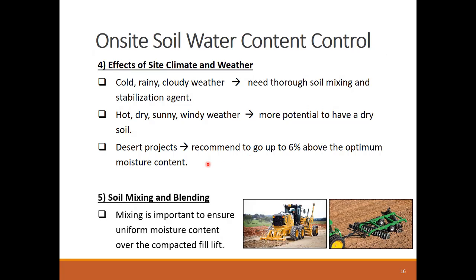Finally, the soil needs continuous mixing and blending to make sure the moisture content is achieved uniformly over the fill lift. This is done using also rippers and harrows.